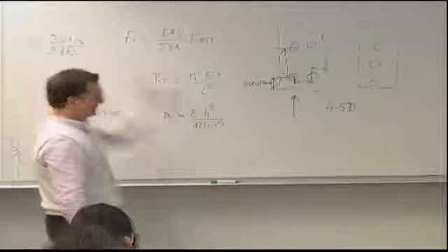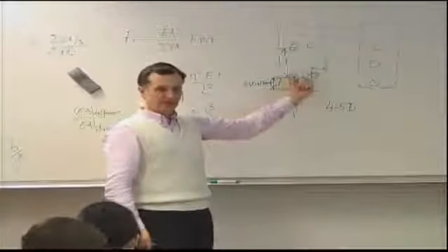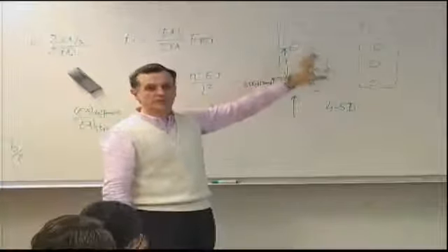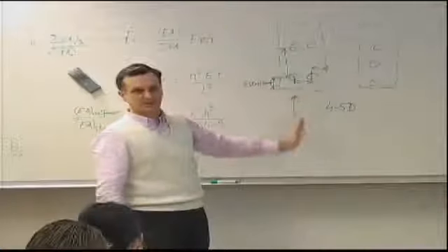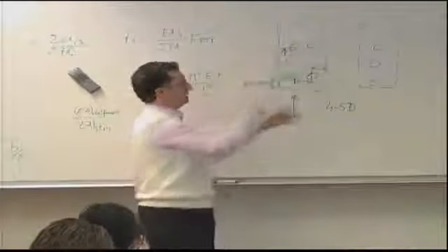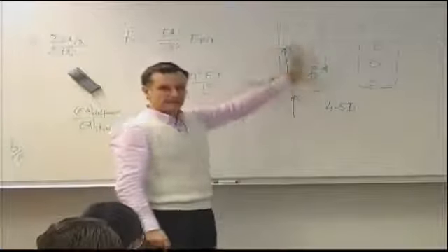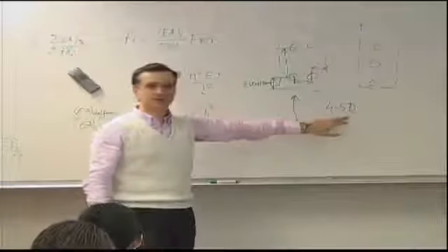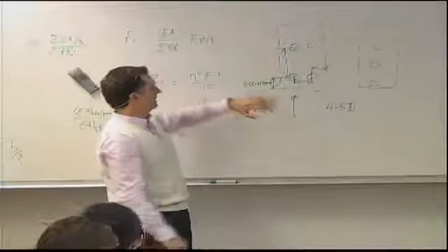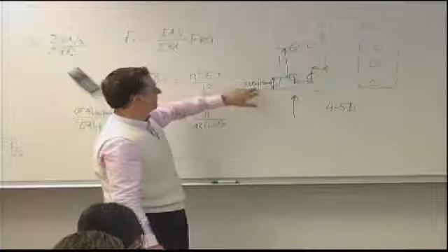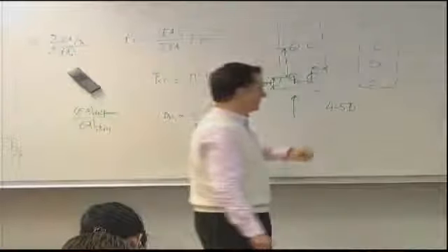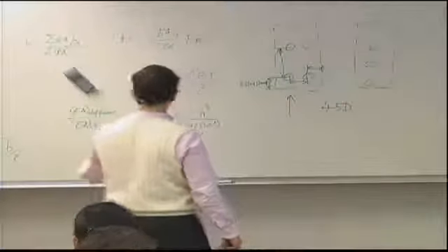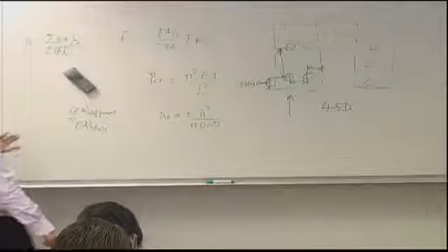In general, depending on the direction of the loading, the spacing between fasteners can be worse in one direction than in another. To avoid having to consider which way is the loading, because this is a simple case, if I had a combined loading like shear and compression, then you actually have to resolve the forces, and that makes it harder. In general, the rule is 4 to 5 diameters, and you are golden as far as this problem is concerned, and 2.5 plus 1.3 millimeters for the edge distance. Now I'm not doing this.